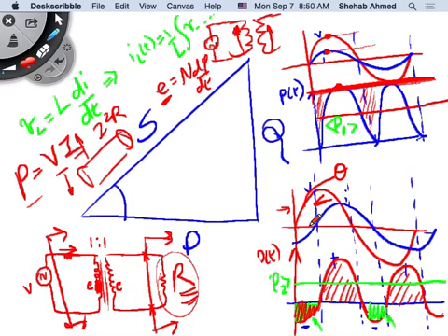So all of these components that have magnetic fields in them require reactive power. And this reactive power does not produce the average torque, does not produce the light intensity, and is not contributing to average power transfer. It is reactive power that is helping set up these magnetic fields. But does this reactive power have current and voltage associated with it or not? If I don't have a load, there will still be current flowing to create this E. Right? So this is the current associated with the reactive power.